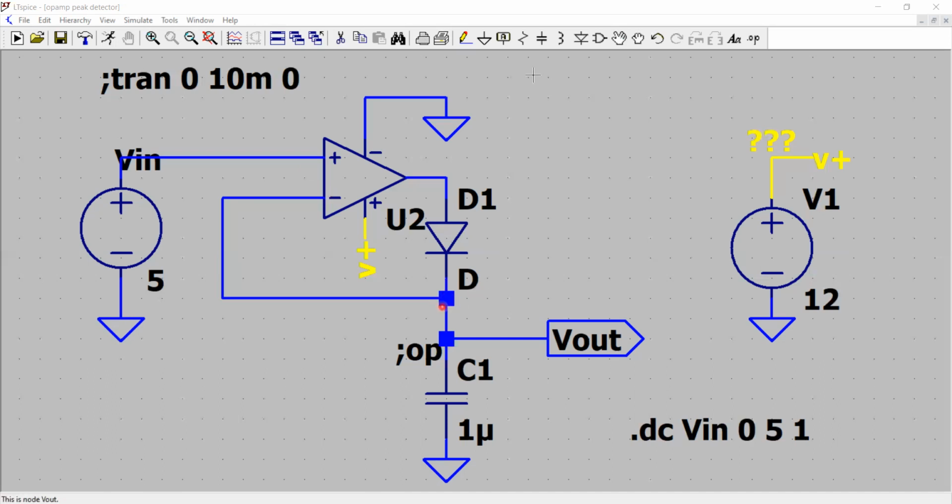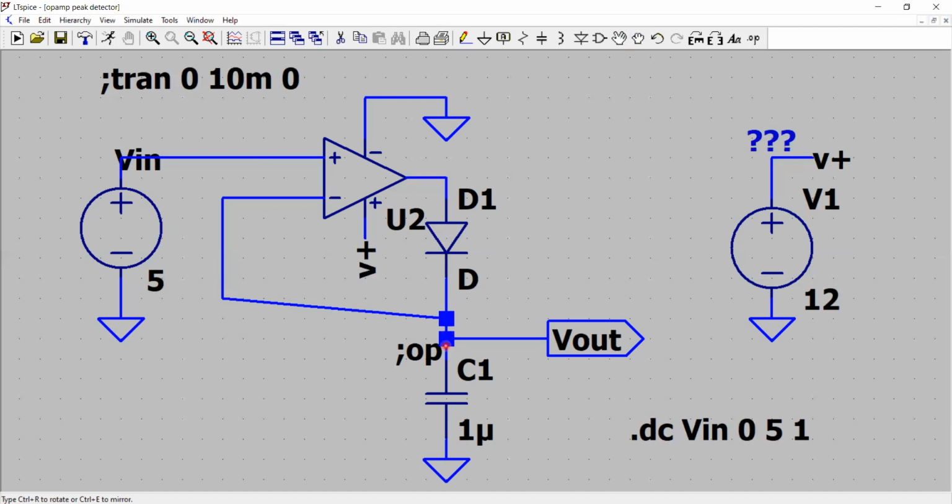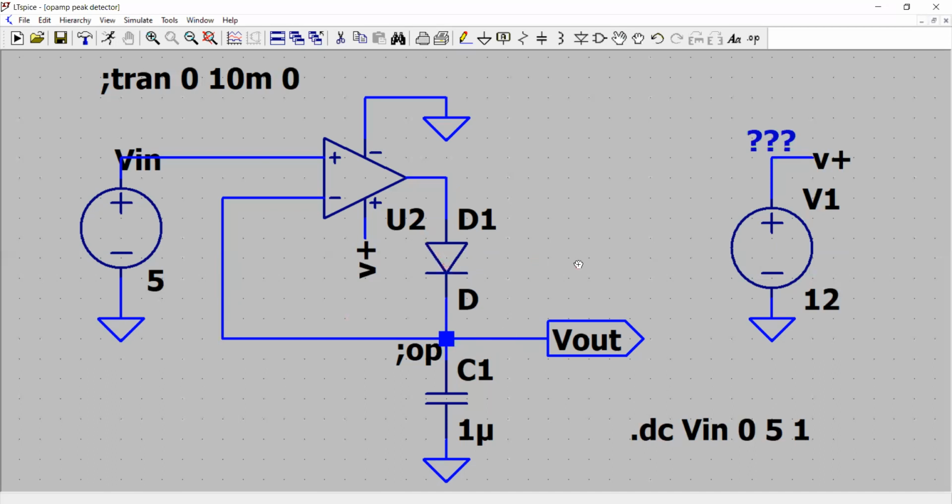So that's correct. Before that, let me just drag this voltage right here, this net I am dragging up. That sounds pretty okay now. And maybe the diode a little bit down. That's okay. So what I'll do, I will run the DC analysis, the DC operating point analysis.